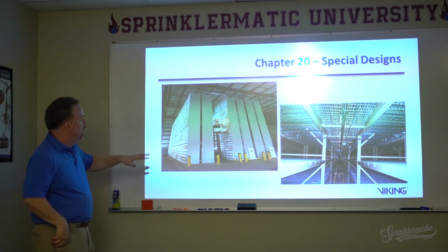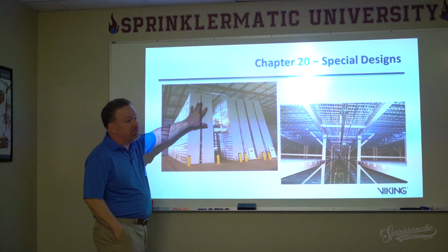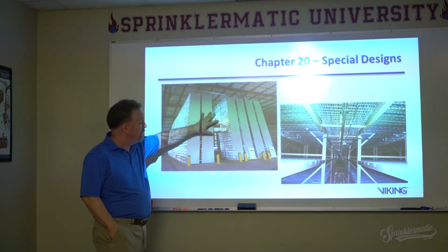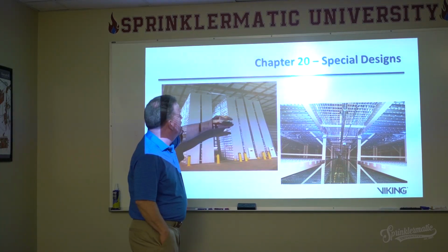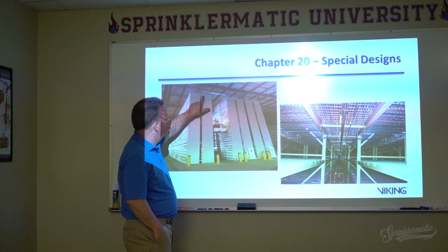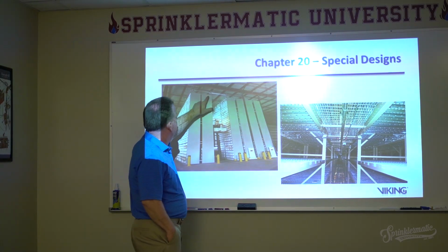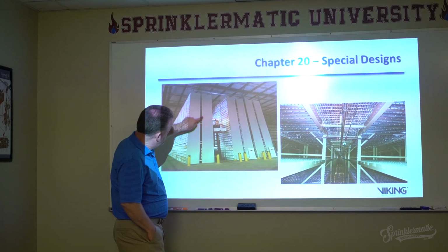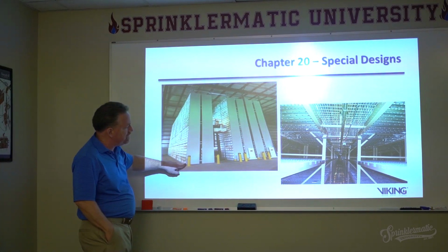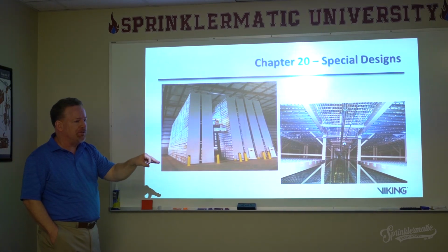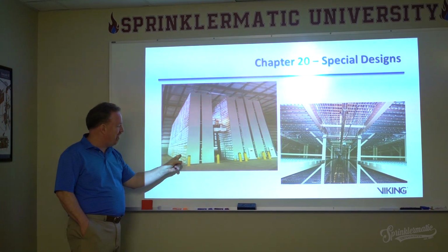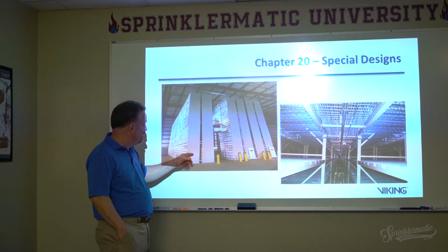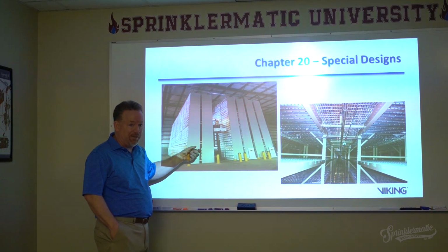Typically, these are protected by ESFR sprinklers as the design criteria. ESFR sprinklers protect this commodity at 40 psi, I think it is. Another interesting component is that the support structure for this unit is required to be hollow tubes. If I get a fire going down here, this is pretty lightweight steel. You get a fire going in here, you can easily collapse this thing by weakening the steel.